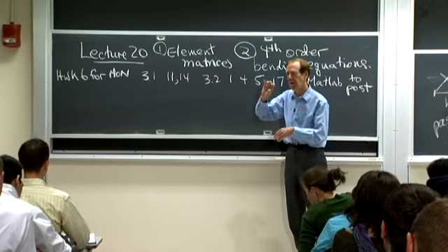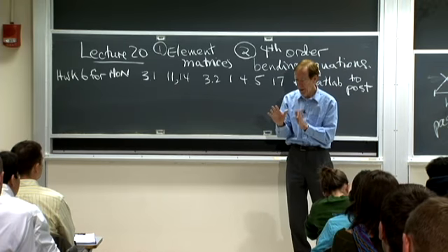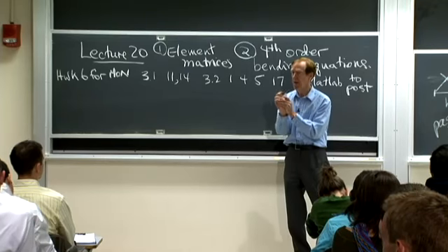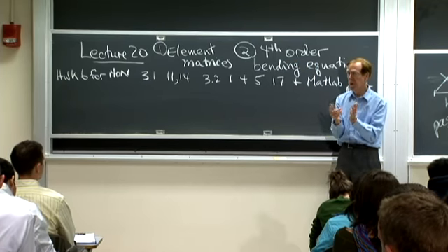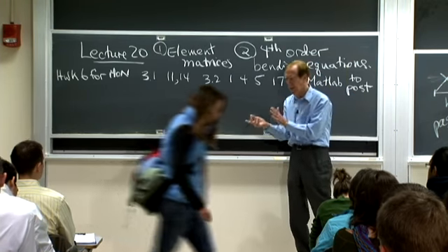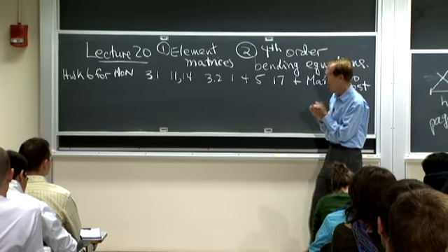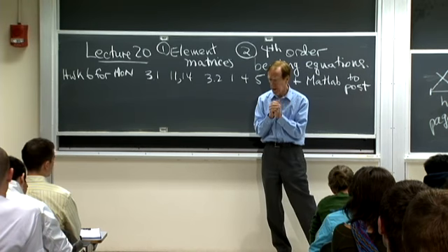So you remember we saw those, that each bar in the truss could give a piece of A transpose A that could be stamped into, or assembled, to use the right word. I think assembled is maybe used more than stamped in, but both okay, into K for graphs.